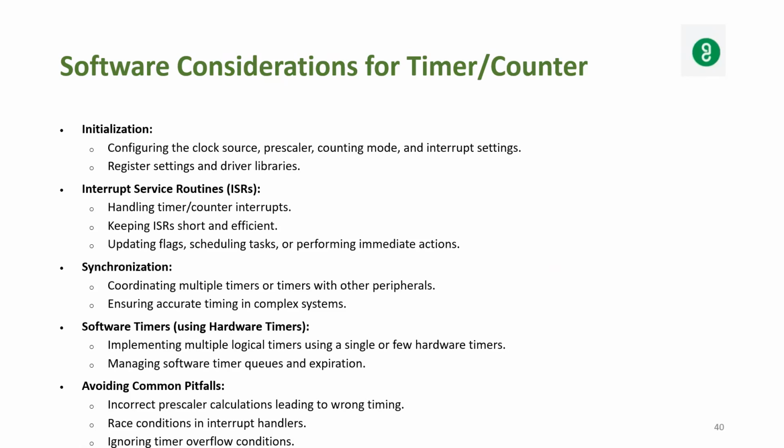Avoid common pitfalls: incorrect prescaler calculation leading to wrong timing, race conditions in interrupt control, and ignoring timer overflow conditions.